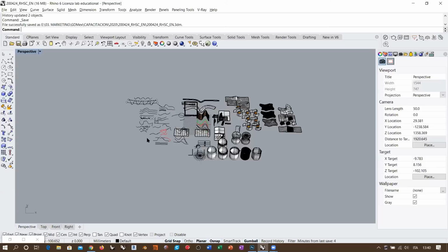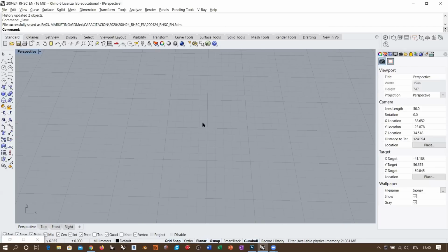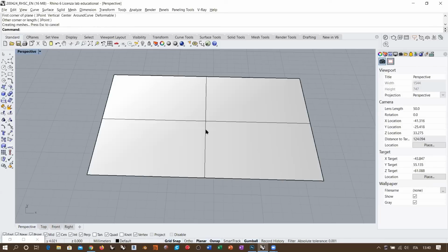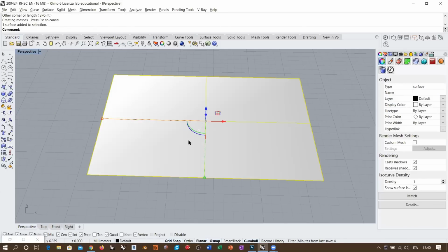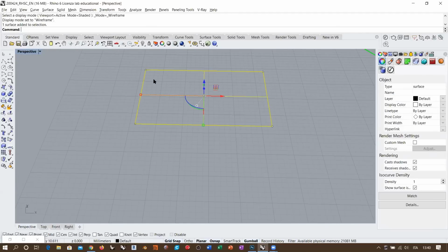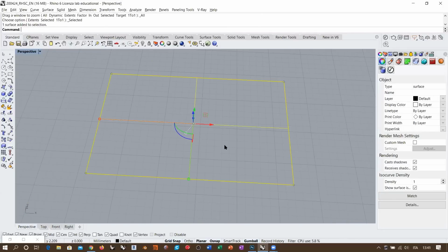So I'm going to make an example with a surface, and I'm going to deform my surface by controlling the knot spans. Okay, and eventually it would be clearer. So let's go here. Let's create a rectangular plane. So bilinear surface. It's not deformable inside because it only has these structural control points. I want to deform this surface from this edge up to a certain depth, and I want all the rest to stay untouched, and deform it organically.